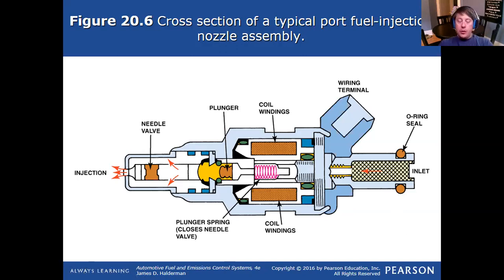In previous chapters, I discussed the final filters that are always in the fuel system. You typically have a sock filter in the tank, and then an inline filter, which could be in the tank still on a lot of these newer vehicles. The sock filter picks up the minor debris before fuel enters the pump, and then from the pump we go to a finer filter in micron, and then from there we deliver all the way up to the fuel rail, and there's always a final filter.